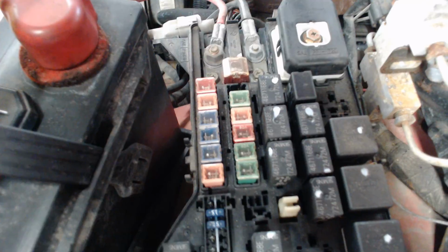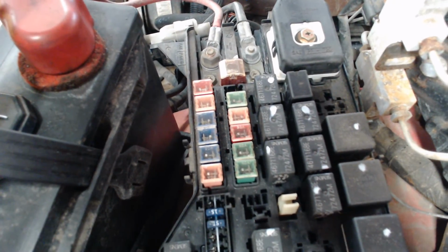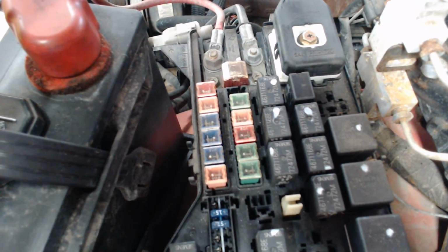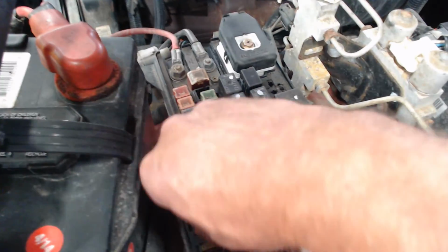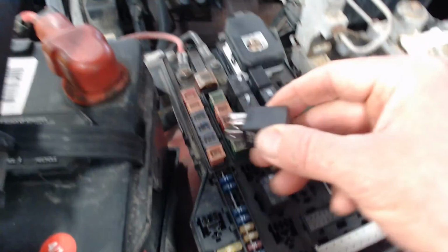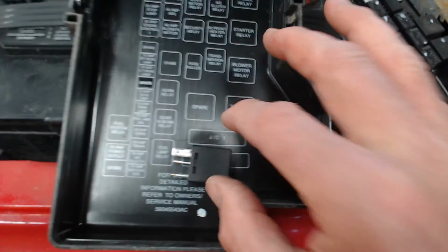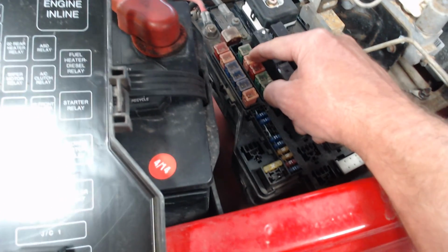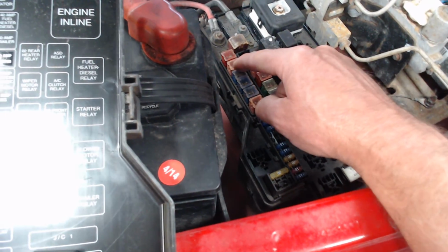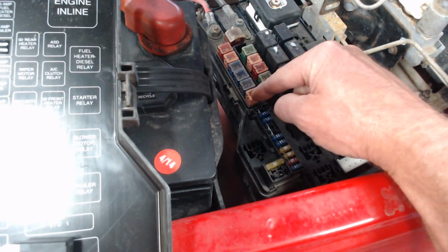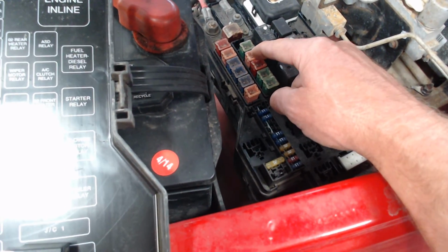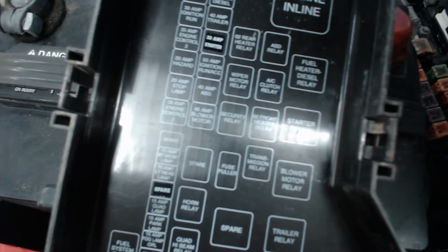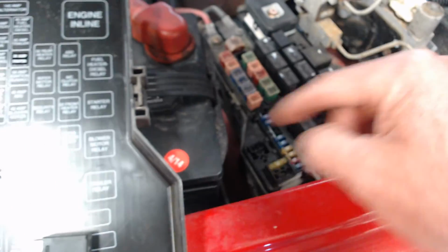And I'm going to pull the 20 amp one that's for the fuel pump relay, or I might just be able to pull the fuel system relay, which is this guy right here. So we'll go ahead and pull this fuel system relay. That might just be a quicker way to do it, and I'll set that over here. But again, one of these 3, this says engine control, this one says stop lamp, and this one right here says it's a 30. Somebody's put a 30 amp there, but it's supposed to be a 20 amp. In any case, we'll pull that fuel pump relay.